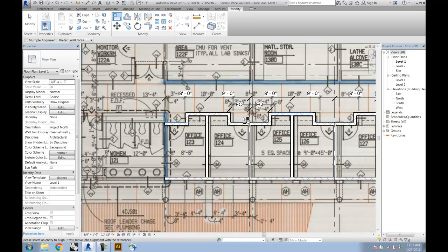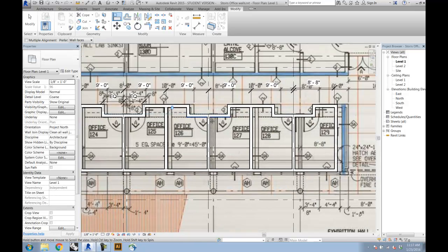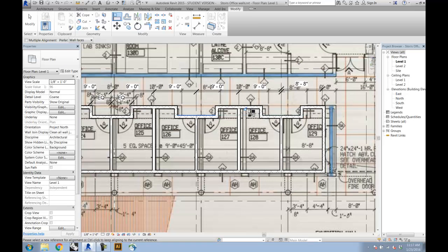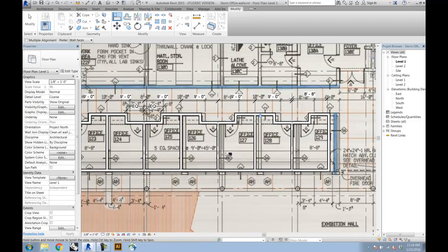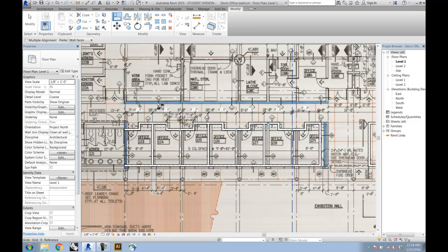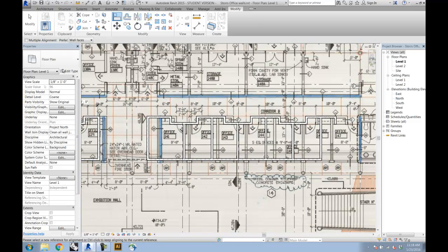And I can do the same for each of these guys to ensure that they're all locked. And these are basically like geometric relationships that you're snapping into place in order to ensure that the system is correct. Okay, now that we've done all that, once we've got one side of this working, then we can mirror it all the way across. So that's actually what I'm going to do.